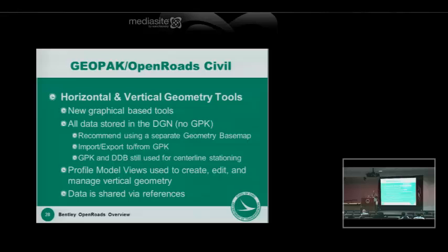I did survey training, and we talked a little bit. The surveyors started looking at those tools, and they're like, how do I inverse between 2 points? How do I do all these COGO functions I used to do? A lot of those functions are still unprogrammed for OpenRoads. OpenRoads is really aimed at getting in that alignment and profile and working on the model. It doesn't have robust COGO tools for everything you would do in COGO.